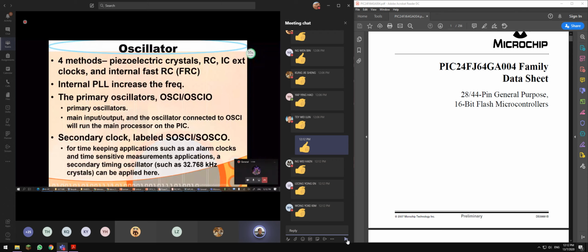As I told you last round, the PIC24 allows you to enable the calendar date and time, according to universal time and the date of a calendar, by connecting these two pins to a 32.768 kilohertz clock. Remember? This means I can set my alarm to ring at 2 o'clock tomorrow morning. It can be done using the PIC24 microcontroller.